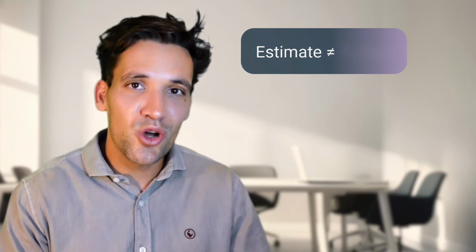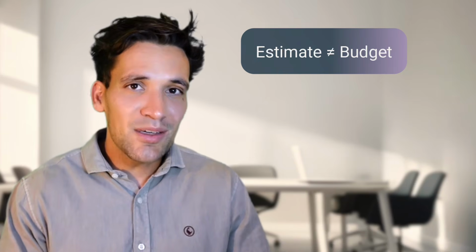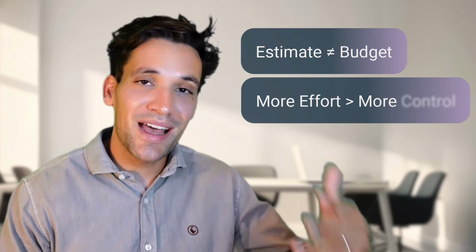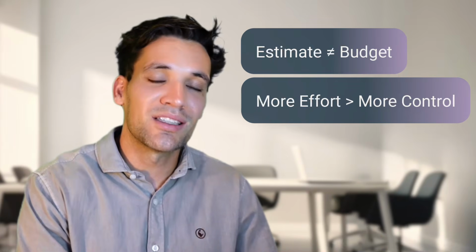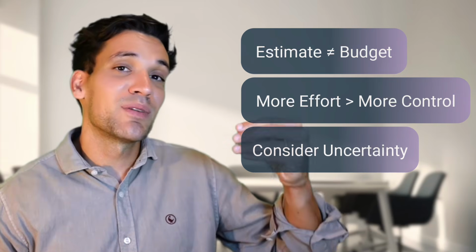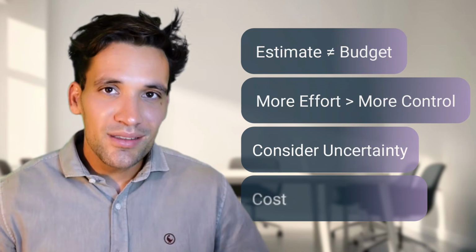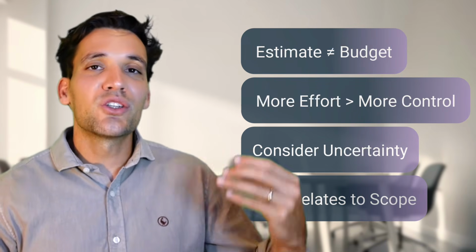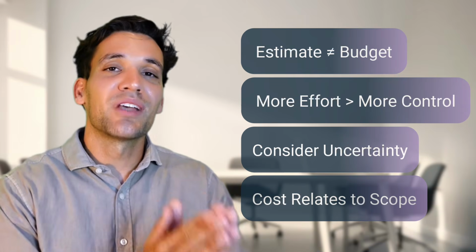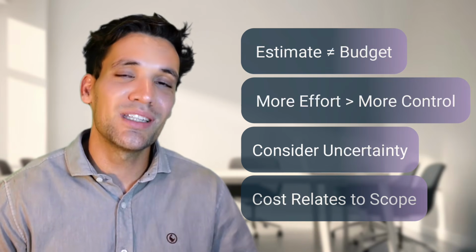As we go through the core concepts of construction cost control, I want you to keep a couple of things front of mind. Number 1, your estimate is not your budget. It's the starting point, but a budget is fundamentally a different tool to an estimate. The second one is the more effort you put into planning and setting up things correctly at the start of the project, the more control you have over the outcomes. But we always have to balance this up and keep in the front of our minds what we don't know and where the uncertainty exists in our plan. And finally, every dollar in our budget, every cost we incur, every contract we sign relates to physical construction work, and we need to understand the fundamental activities that are driving costs.